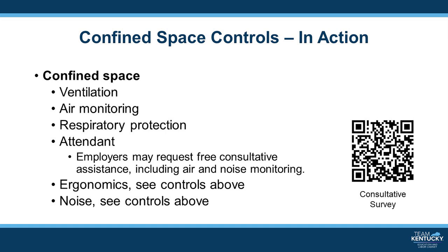If in the confined space, rusting or rust is occurring, or other decomposing biological material is inside the confined space, this can use up and deplete the amount of oxygen inside the space. In many cases in a confined space, mechanical ventilation is necessary in order to ensure that the air contaminants from welding are maintained below the permissible exposure limits. Respiratory protection may be required, and depending on the type of fumes being generated, the type of respirator could vary.